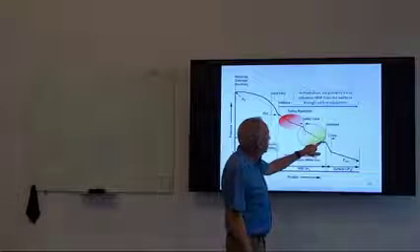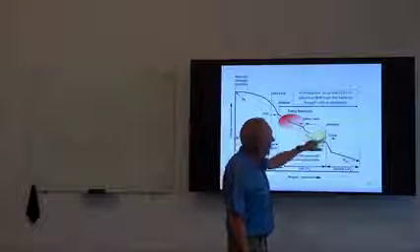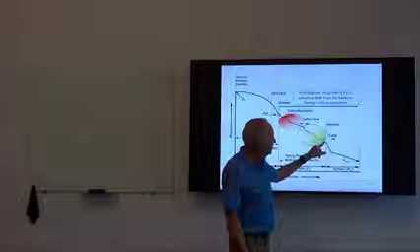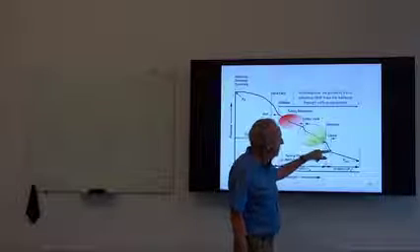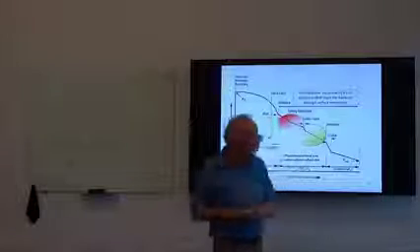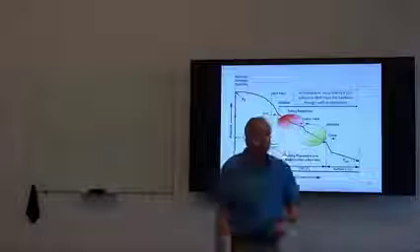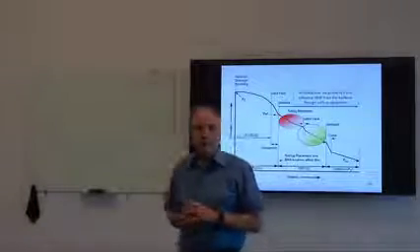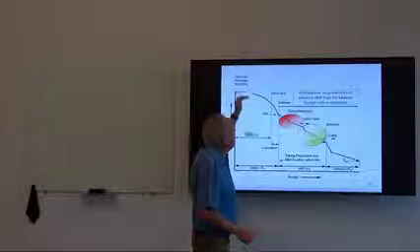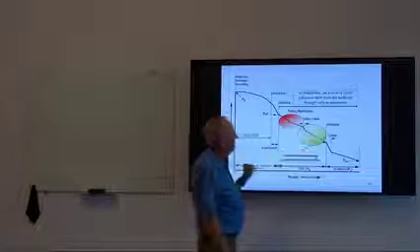We get to the surface, and we have our wellhead, through whatever our wellhead piping is, surface piping is, through the choke, and then across to whatever our desired delivery point is. Here it's referring to the separator, pressure at the separator. So it is a case of trying to manage pressures all the way across the system.